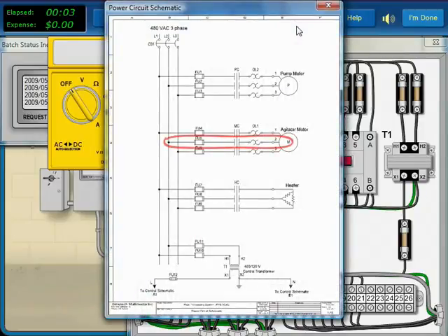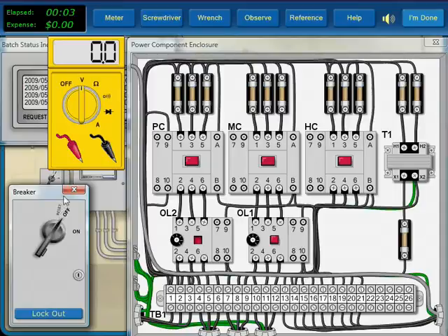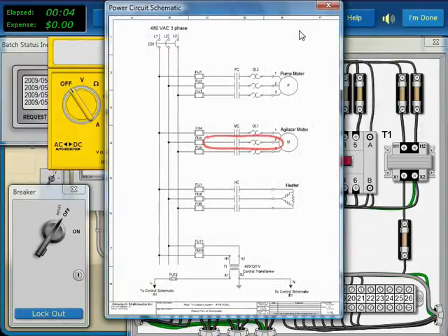In the new problem area, the fuse is now the best place to test, as a blown fuse is an obvious probable cause. To safely test voltage in the power circuit, we open the breaker each time we place the leads. The readings all show full voltage, indicating the fuses are okay. We now know that the fault is an open in the center phase, somewhere between the bottom of the fuse and the motor start point.